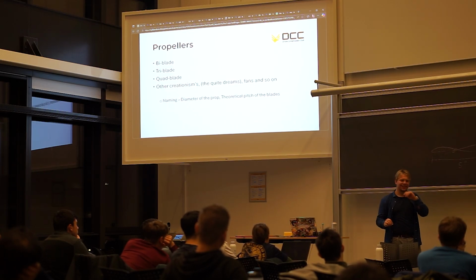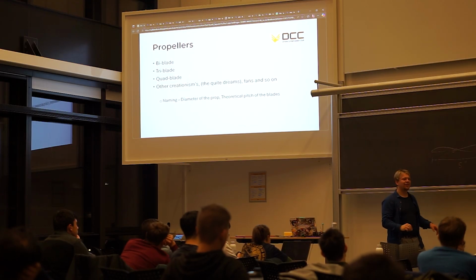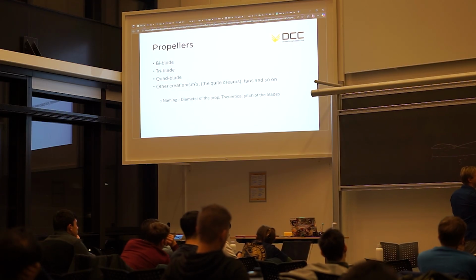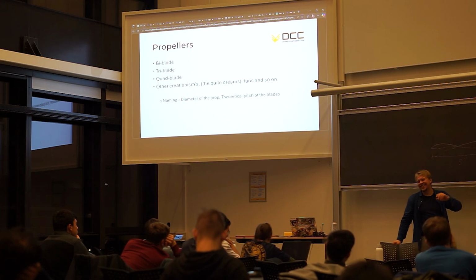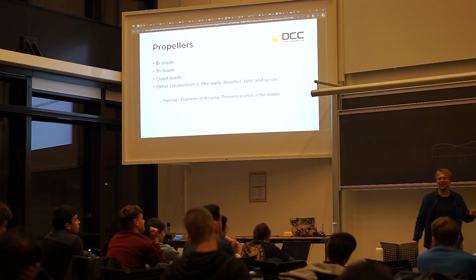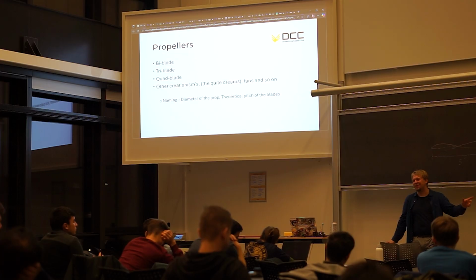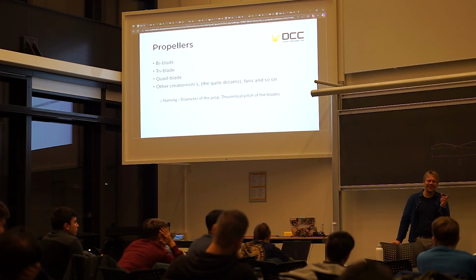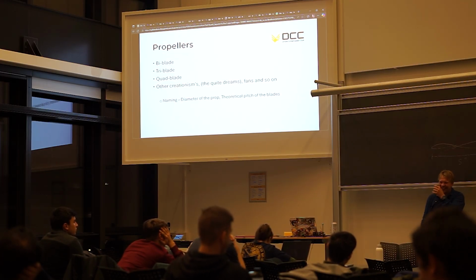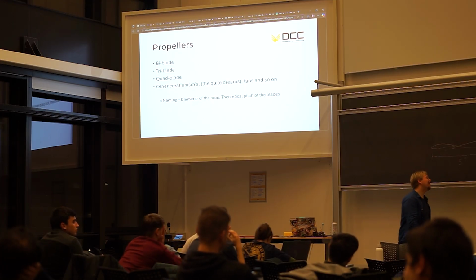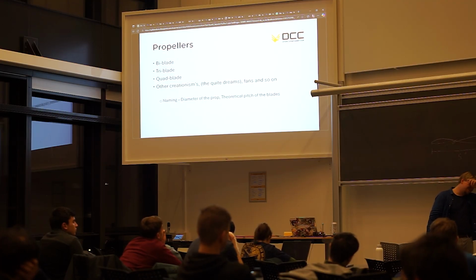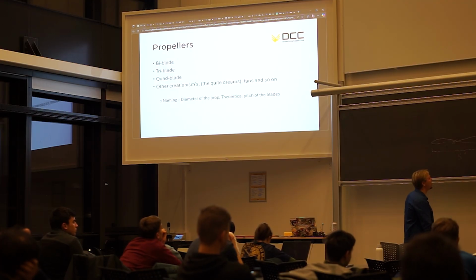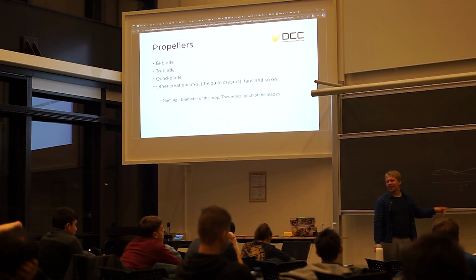Now, there's also another thing. If you go down to small sizes, if you see 30, quite often this is not in inches. It sometimes is in millimeters. There was a semester project group that bought a motor for a 3-inch propeller, and they bought a 30mm propeller, and they were thinking that it's a bit weird and odd. So check your units.